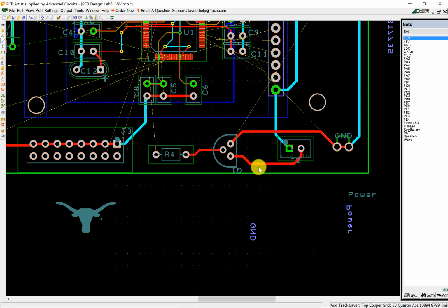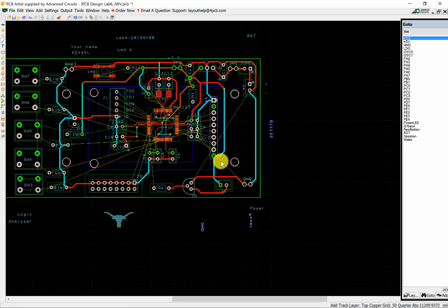All right. So if you look at the speaker current, by the way, you will see that the plus 3.3 is a 20 mil trace right off of the regulator down to the speaker, across the speaker, back to the transistor, back to ground. See, the speaker current is in this loop. Doesn't go into my processor, doesn't go into my delicate stuff. All right.